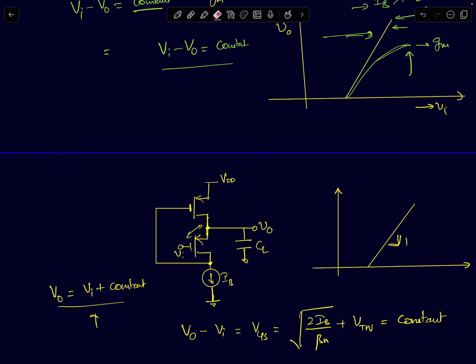I've shown here an example of a flipped voltage follower. Sorry, I'm using a PMOS follower to illustrate the point. You'll understand why I'm doing that in a few moments. If you see, a flipped voltage follower has a source follower device. In addition to that, you also have a feedback device, a common source amplifier in feedback. Previously, the drain voltage of the source follower is always held at a constant voltage. That's not changing at all. Now, instead of that remaining constant, we are taking that and feeding it to the gate of another device.